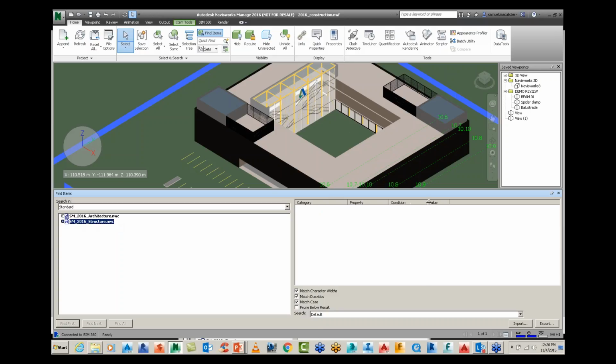It's always good to maybe have two screens sometimes for our products because they've got a lot of functionality within them. So here when you click on it, you don't actually see the menu. You've got to actually click on the blank space here on the right to bring it up. If I go and click on Item, you can see there are numerous other categories you can choose from, and then go next to Property being Name, and then Condition equals, and then Value. So these are all the values that Navisworks is reading from certain parameters of my model.